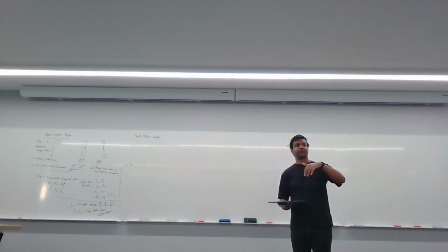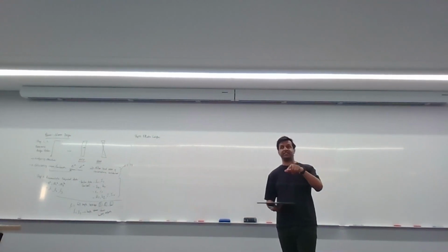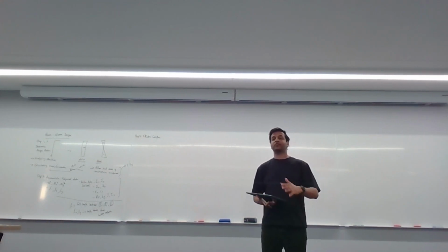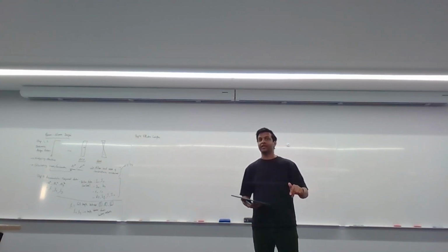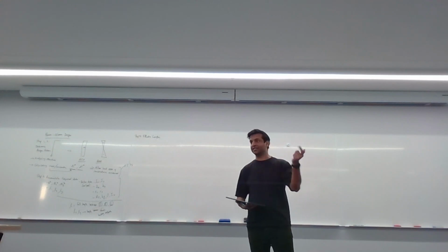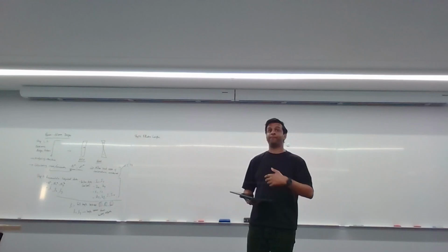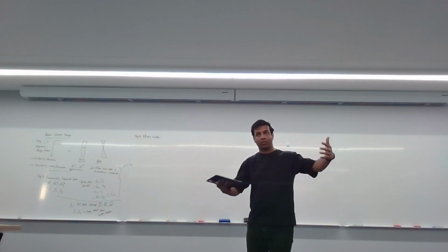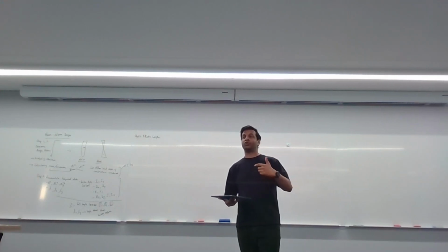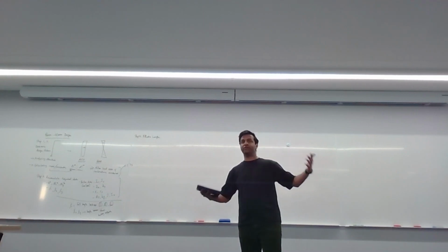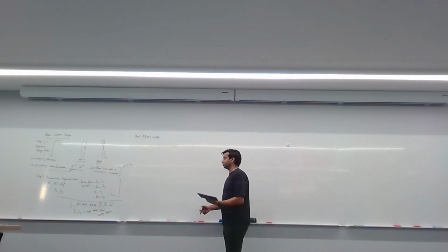And then figuring out which one's the critical segment. Because if you really want to design a steel section for flexure, the most inefficient thing you can do is check every single segment or sub-segment. Especially under the time crunch of an exam, the point is to test whether you can look at what's given to you and figure out which one's the most critical one, and then you check that one. If you size it for the most critical one, then you're good for the rest. So I'll go through that later.